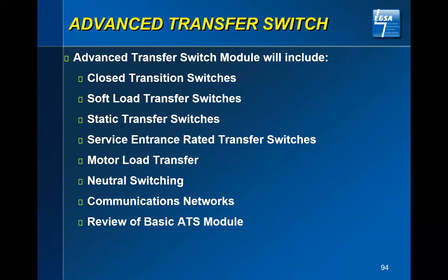If I take my generator set and do the same thing separately out in the yard, I take the neutral, bond it to ground, and drive a ground rod out there, now I have two references to ground, and I must switch that neutral so that only one source is connected to ground. That is called a separately derived source, and it is covered in detail in the advanced class.